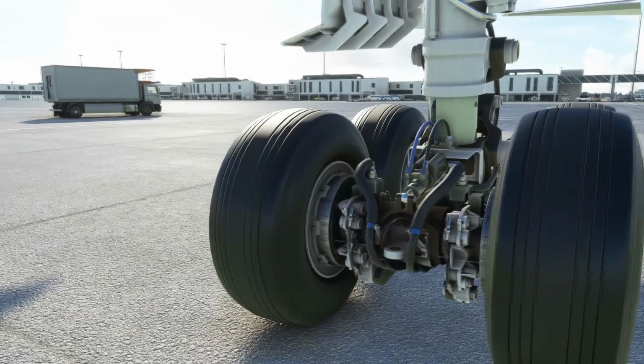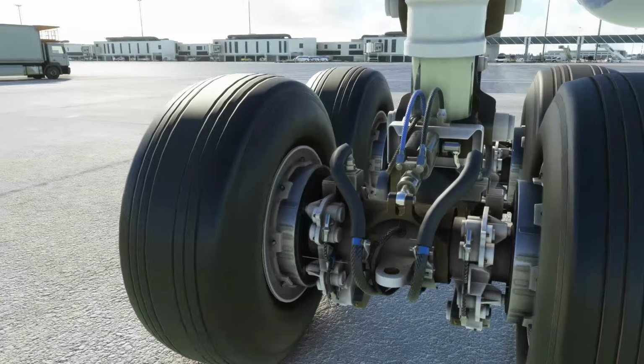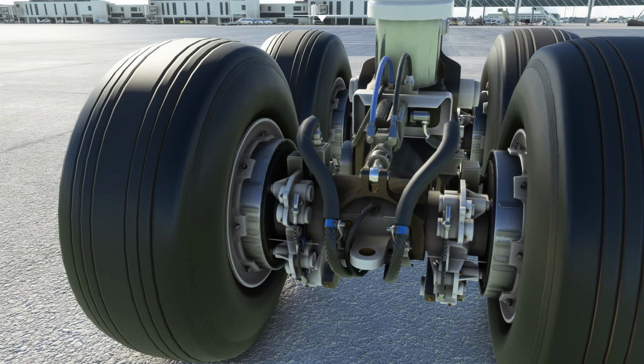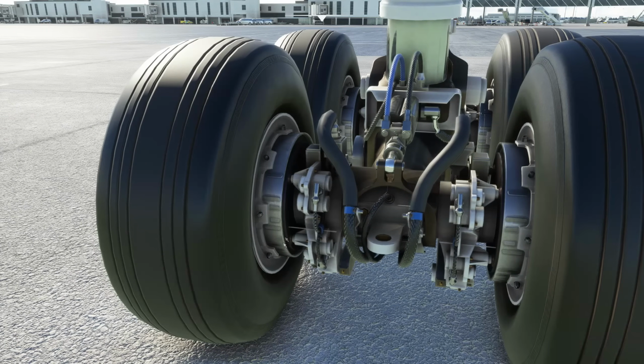As you can see, it's got lots of cabling, and normally we're checking, of course, for a few things, one of which is the brake wear pins. We want to make sure that these stick through slightly, otherwise the brakes have run out. As the brakes wear, they move down. Pretty standard carbon brakes that you get on commercial airliners. I'm not sure if they're ceramic, but yeah, the brake system, however, is again very different.